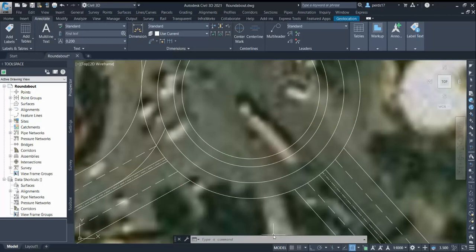You can go for a minimum of 3 meters for a single lane roundabout. Maximum entry width should be 10.5, and for a 2 lane roundabout, maximum entry width would be around 15. So you have to play between those minimum and maximum values, and also consider the vehicle tracking.